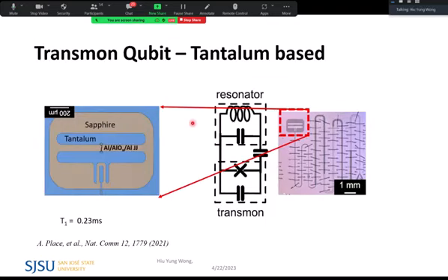Here shows the layout of a transmon from this paper. This is the IC layout. You look from the top. Here, the gray parts are just the insulator, the sapphire substrate, just something to hold the device. This very tiny thing you cannot see is the Josephson junction. Aluminum, insulator, aluminum. That's it. They form a junction there. That is the whole Josephson junction.